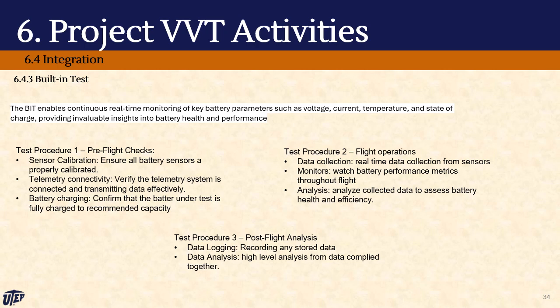Built-in test. The BIT enables continuous real-time monitoring of key performance parameters such as voltage, current, temperature, and state of charge, providing invaluable insights into battery health and performance. There are 3 primary procedures for the BIT. It is broken up into pre-flight, flight, and post-flight, as shown below.